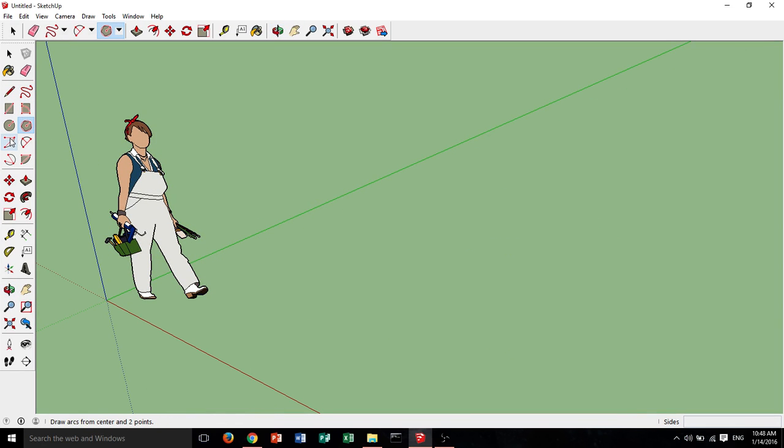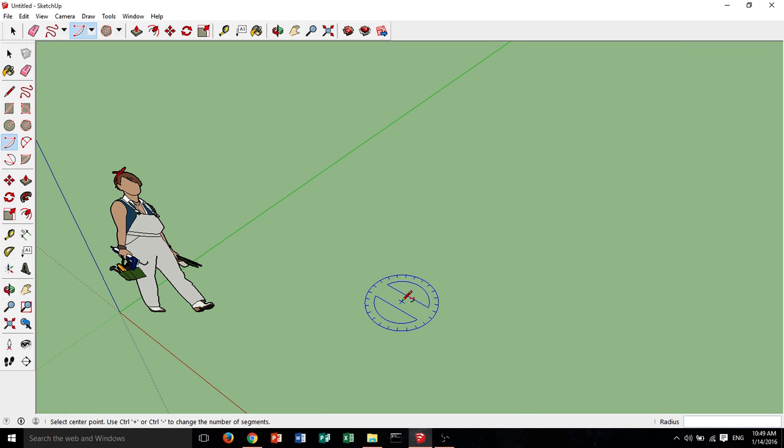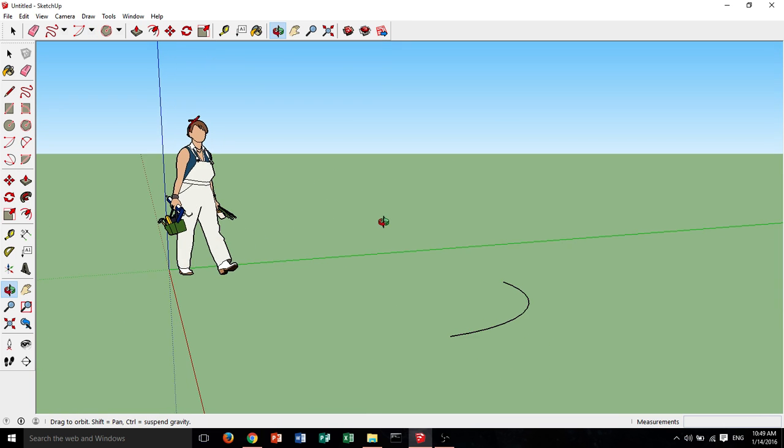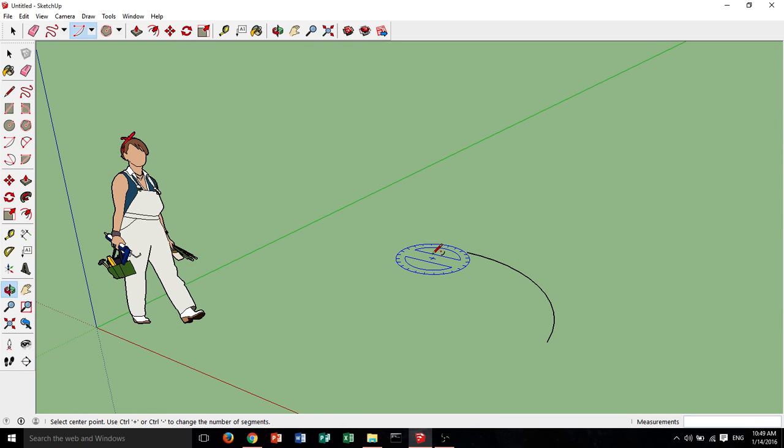Now if we continue down, we have new kinds of arc tools. I called it the curve tool before, but there's a 2-point arc, which I showed in the last video, where you can just kind of arc any direction you want to. There's also the default arc tool, which can create a complete 360 or to whatever degree you want off of the protractor right there. So this can be helpful for making exact, perfect 90-degree curved corners.